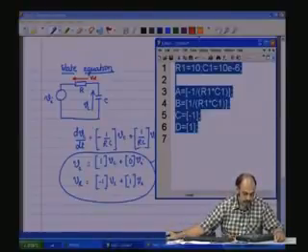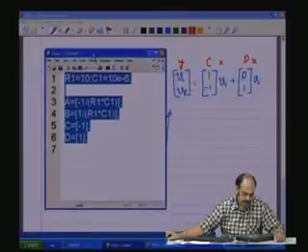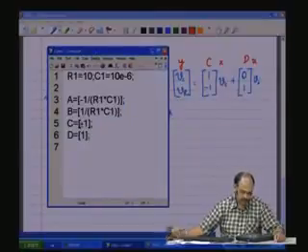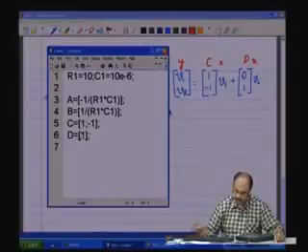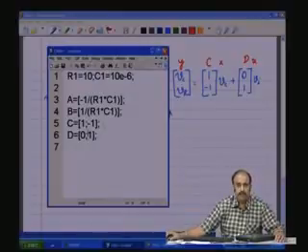So, what do we do here? You see the C matrix is 1, 0; semicolon is next row, minus 1; D is 0, semicolon is next row, 1. So, by just modifying C and D matrices, now you are able to see multiple outputs.